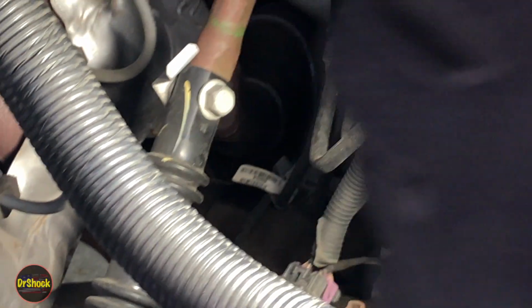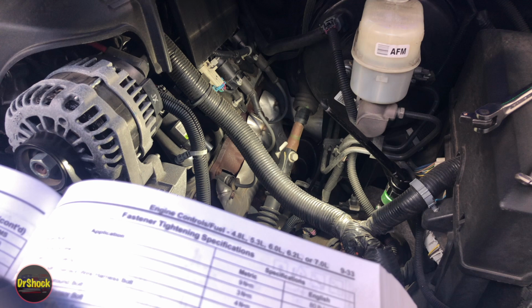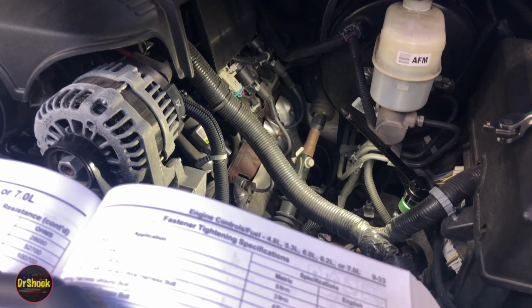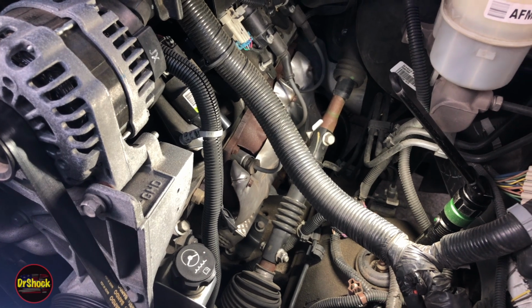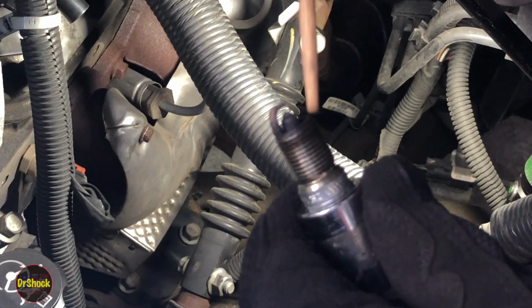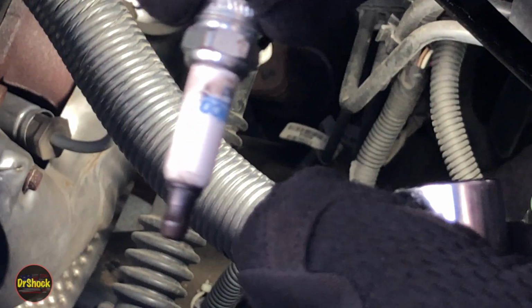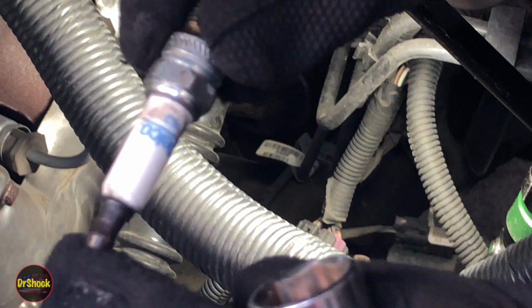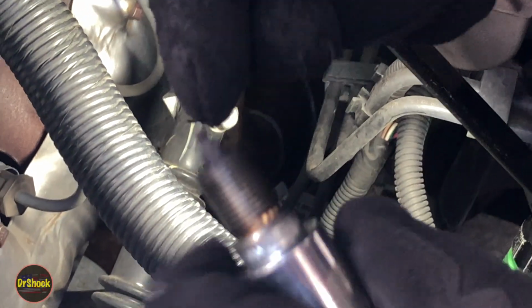Let me grab my little wooden probe that I had here before. Don't know where I misplaced it to. Give me a sec, guys. There it is. Don't want to touch this with anything metallic. But if we zoom in on the plug here, these are AC Delco 41-162s, I'm sure. Yep, 41-162s. And there's oil on the plug threads, right? So like I said, no surprise, this is an oil burning engine.